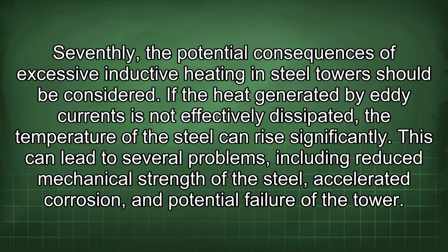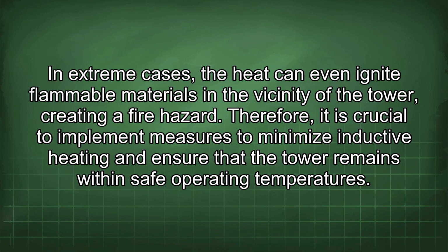Seventhly, the potential consequences of excessive inductive heating in steel towers should be considered. If the heat generated by eddy currents is not effectively dissipated, the temperature of the steel can rise significantly. This can lead to several problems, including reduced mechanical strength of the steel, accelerated corrosion, and potential failure of the tower. In extreme cases, the heat can even ignite flammable materials in the vicinity of the tower, creating a fire hazard. Therefore, it is crucial to implement measures to minimize inductive heating and ensure that the tower remains within safe